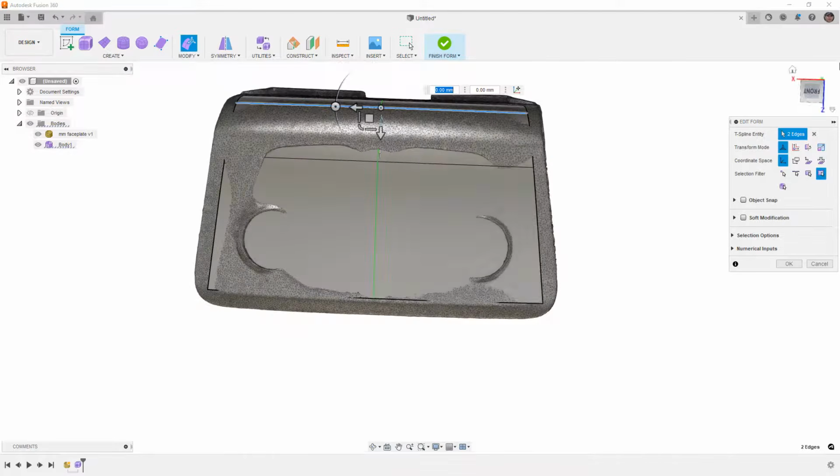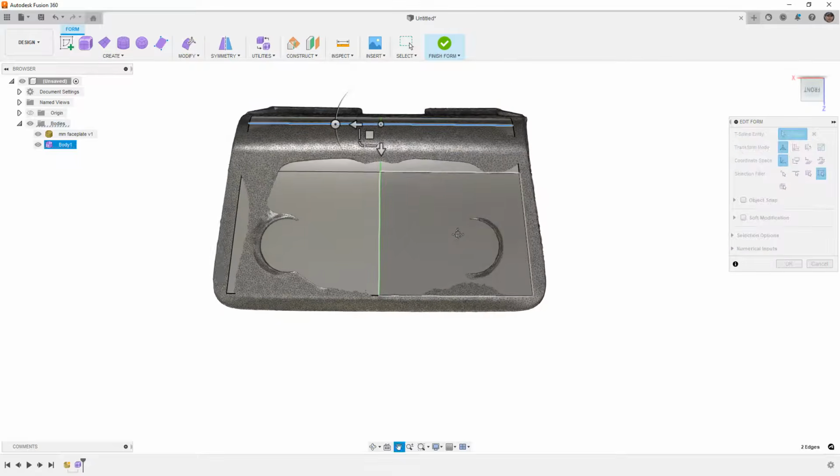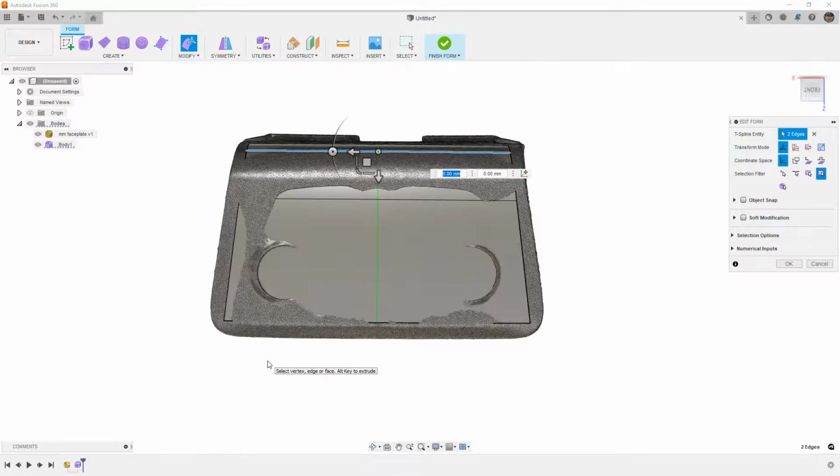This is also a good time to take a look at this and note that we 100% do not have a symmetric mesh, which could mean that the mesh or the part itself is not symmetric, but more likely is that it's not perfectly aligned to the coordinate system. There are some things that we could do, but it's going to take a lot of time, and generally mesh software ends up doing this much better than a manual approach.